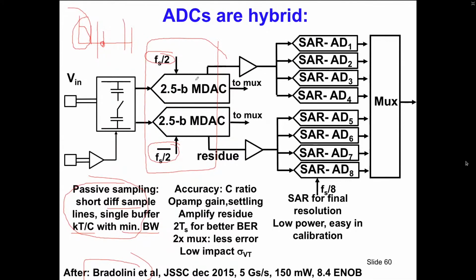So this is very smart to do with a ping pong architecture. Then the MDAC structure allows you to reduce the amplitude. And that means that here you can concentrate on a relatively small circuit and optimize the entire accuracy of your system.